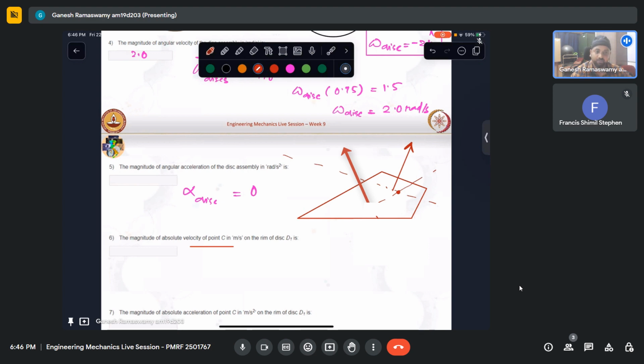If it falls within the body, it is having fixed axis rotation about that point. So naturally, the velocity of that point cannot be non-zero, right? Unless it is some transient analysis, it will have to be zero, because that is by virtue of which we are connecting this. We are saying that this has no velocity. In such a case, if this is r, this has to be perpendicular.